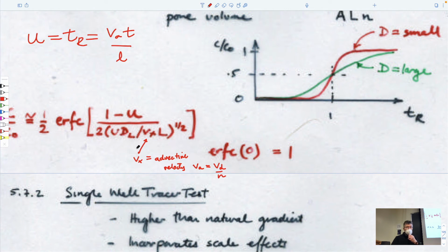And actually it's a derivative of Peclet number, right, as well. So Peclet number is equal to velocity times L over D. So that's this term here. This is 1 over Peclet number. And so this is dimensionless. So the Peclet number is the ratio, just like Reynolds number is the ratio of inertial to viscous forces.